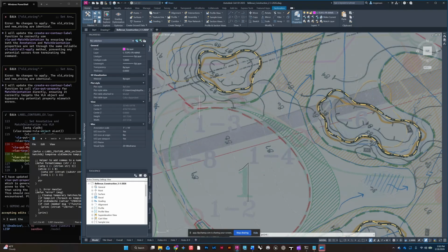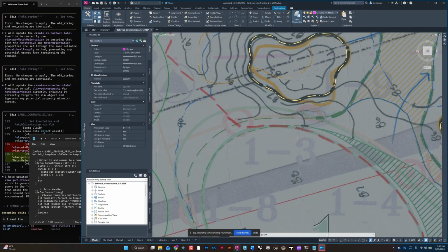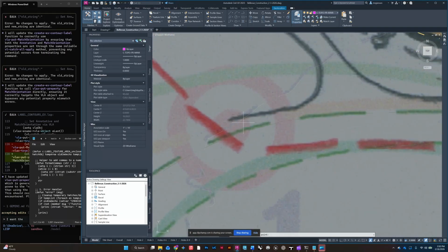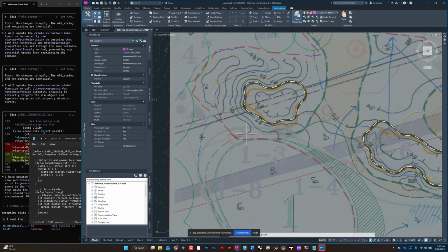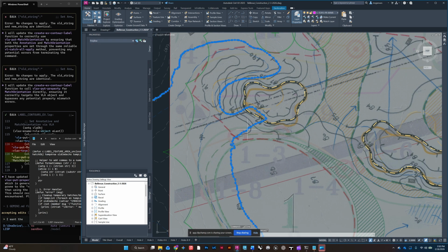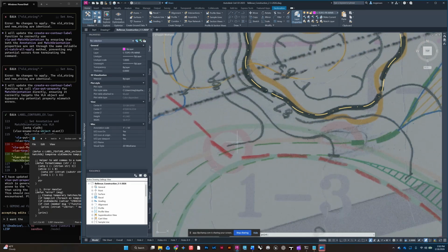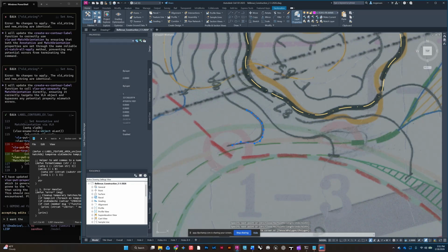I'm just going to use a normal polyline, and one of the keys is making sure that you don't just click near it. If you just try and click on it like this, it's not going to take the properties, because, let me show you, this polyline has an elevation of 89 in its properties. If I try to just click close, even if I got perfectly on it, this new polyline has an elevation of 0. It doesn't have that data in there.